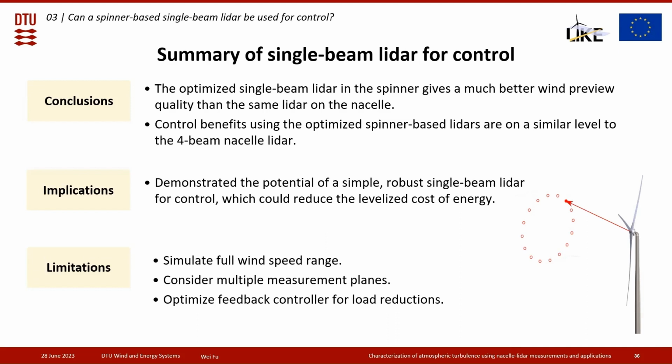This work has demonstrated the potential of a simple, robust single-beam LiDAR for wind turbine control, which could eventually reduce the levelized cost of energy. The limitation of this work is that in our simulation, we just consider a single wind speed, but the full wind speed range could be simulated to better evaluate the control benefits.